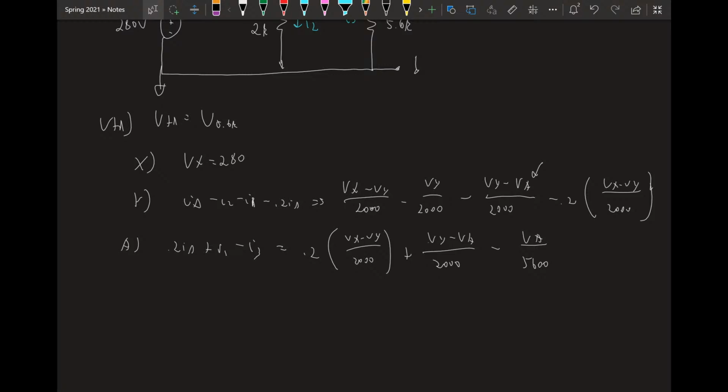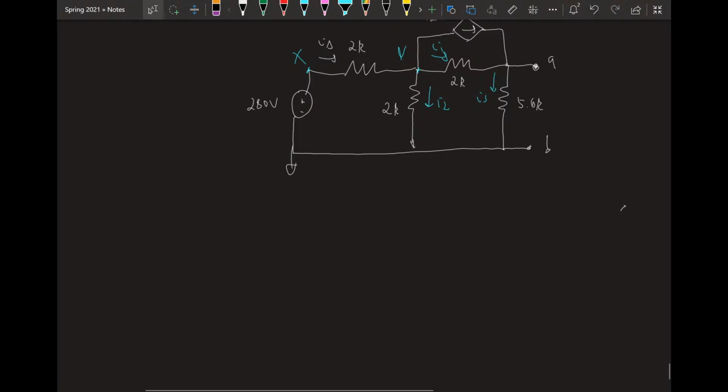It's a bit far down, but let's solve for I Thevenin. So for I Thevenin, we're going to short the circuit, right? So we're going to say there's a short circuit coming over here. That shorts out this 5.6 kilo resistor. It's now gone. But we still want to solve for this short circuit over here.